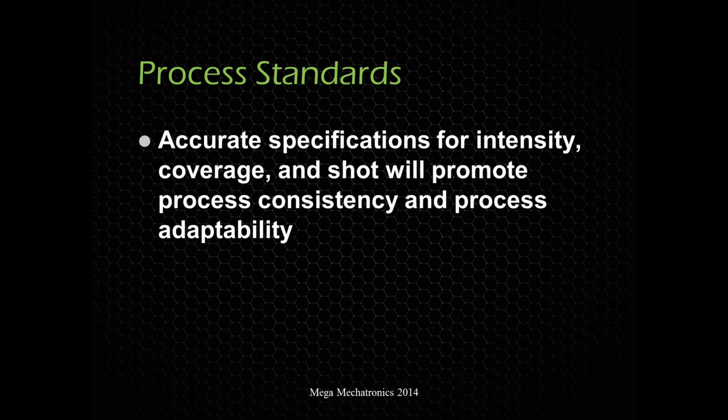So you need to create accurate specifications for that intensity, those almen strip measurements, those residual stress parameters, as well as coverage. So that's going to be the time. Time is very important. As well as specifying the correct shot and ensuring the correct shot gets put in the machine. Otherwise, you're going to lose all those benefits. It still might increase the fatigue strength, but you're going to lose your safety factors. Or you're totally going to negate them if someone puts the wrong shot in the machine.